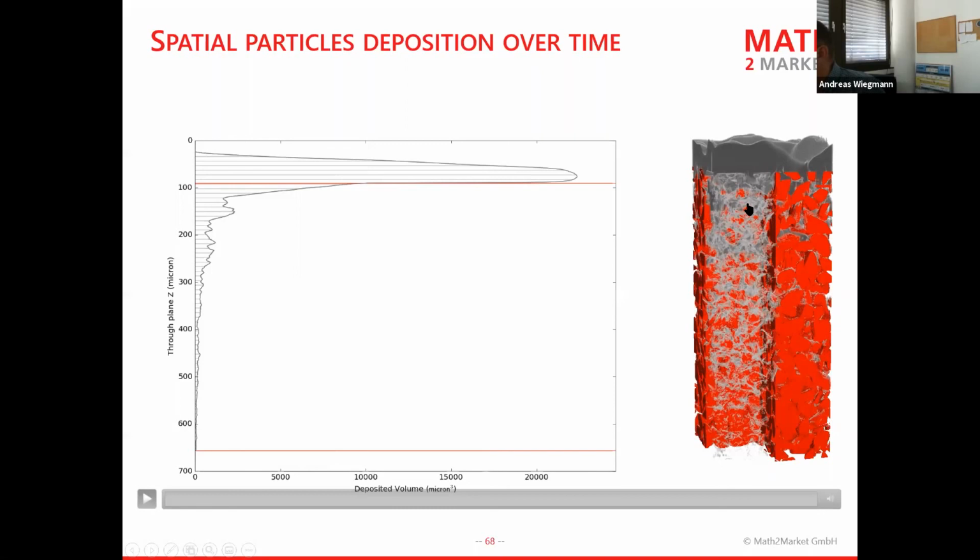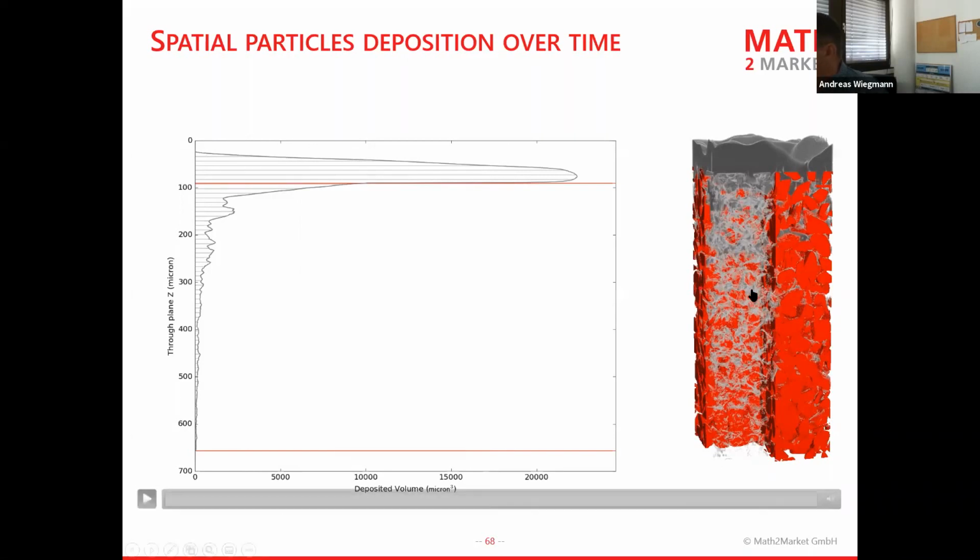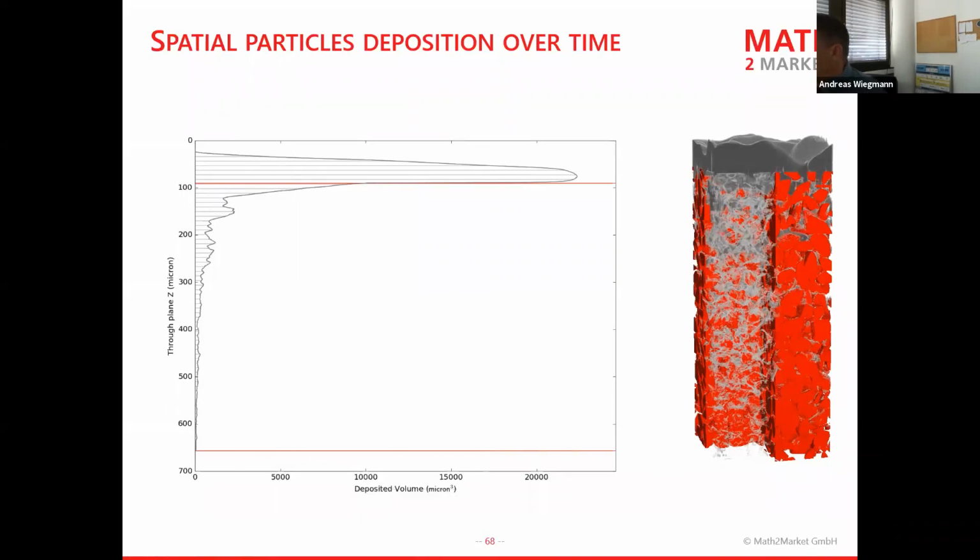We have all kinds of effects, like very small particles can even have random motion to them. Once they are below a couple of microns, random motion will start to play a role. They will not just go with the streamlines, for example. Or if they're large particles, they have inertia. So those particles are being tracked with the flow, and then when they collide with the red parts in this image, with the grains, you have to make a decision. As I said, soot will just stick, and that's great. And other things may bounce off and go deeper.